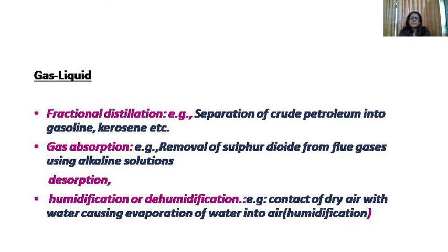Next, desorption is a reversal of the absorption operation. That is, if you contact a gas with a liquid solution, and a component gets transferred from the solution to the gas, then the operation is called desorption or stripping.